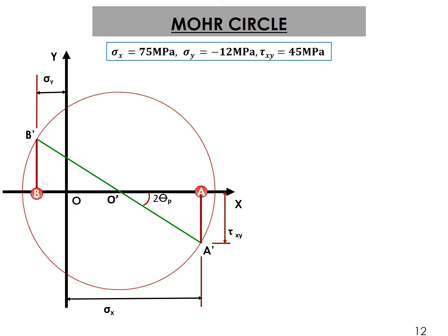Now again, the basic Mohr circle I have shown here. What is to be found out now? Now see, what is this twice theta? If you can remember the last part, you have to find out the stresses when the angle is rotated counterclockwise at 30 degrees. And I have told you, when you are working with Mohr circle, you make it twice theta always. Just remember it. Theta with the element, and when you come to Mohr circle, make it twice theta. So we have taken twice theta counterclockwise with your axis. As I've told you, the green line is your axis. Now this green line basically rotates. Your axis is rotating only.